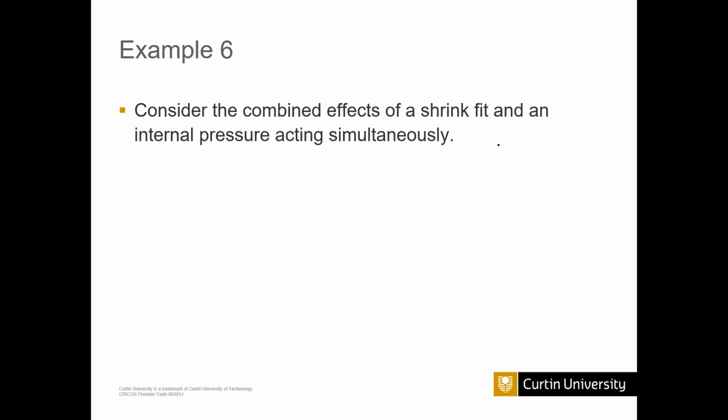When you do the calculation or the questions, you will easily see some kind of feature. So you can do the calculation even though it's a compound cylinder. Consider it as one single cylinder, do the calculation, calculate the contact pressure separately and get the summation.